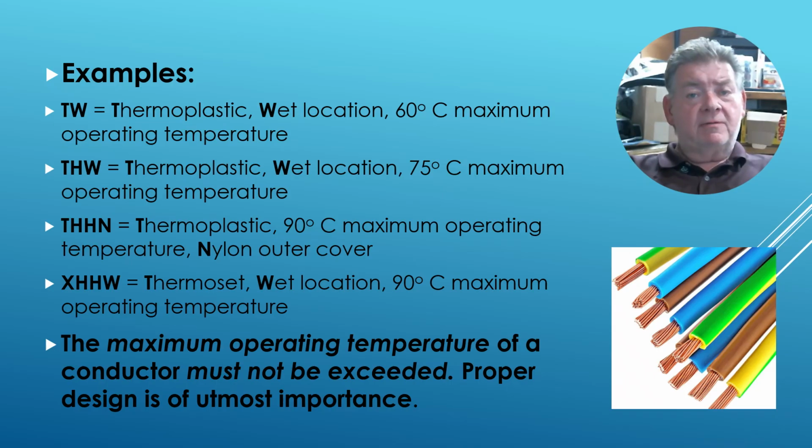But just be careful because sometimes in the larger size conductors, you might just get straight THHN insulation. And if that's the case, you're not permitted to install those conductors in a raceway underground.